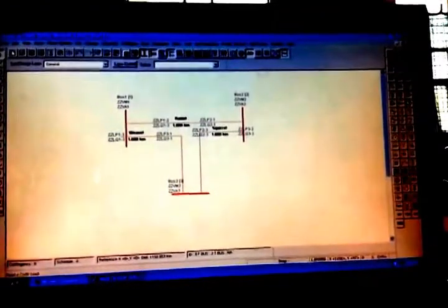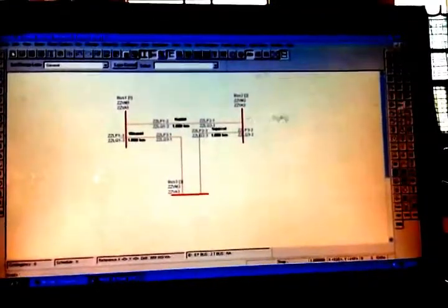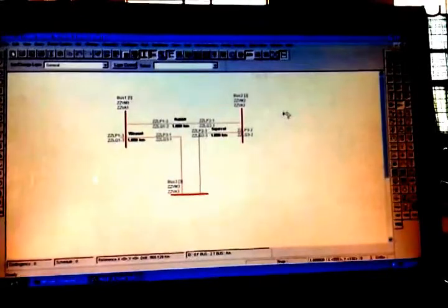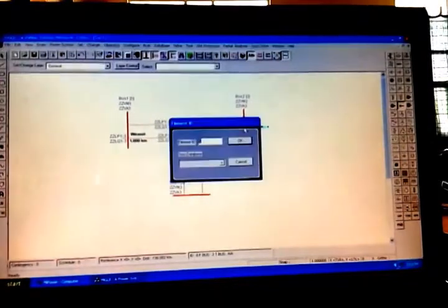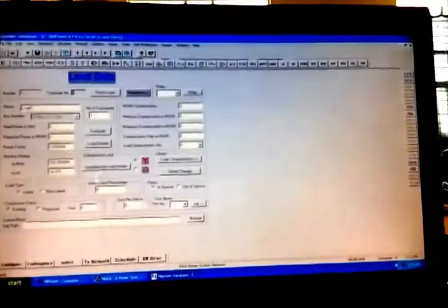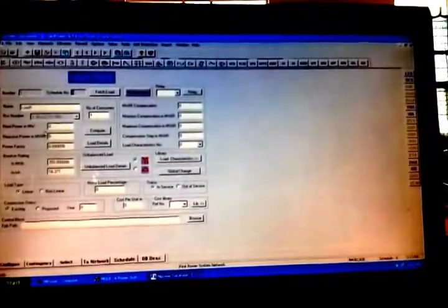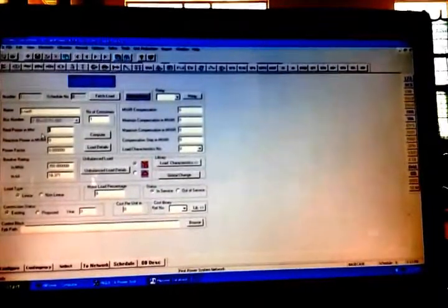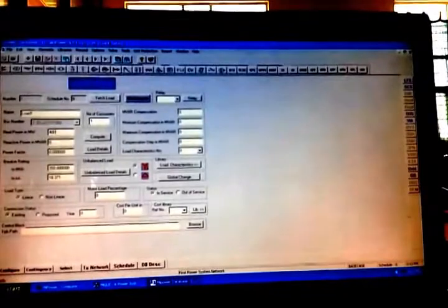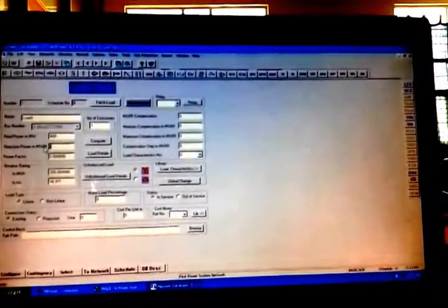Let's go for the load. Select the load. So this load is in the required direction. So place it directly on bus 2. Give OK. So the load doesn't contain any library. So directly enter the value. Real power in megawatt given is 400. And reactive power is 250.